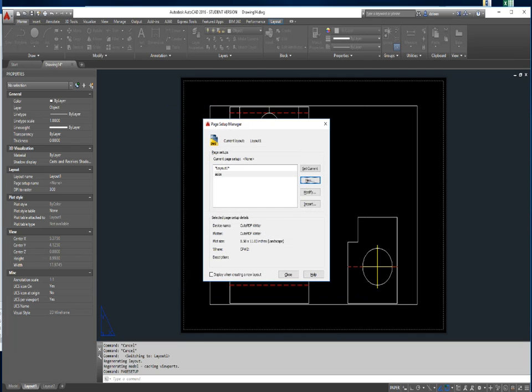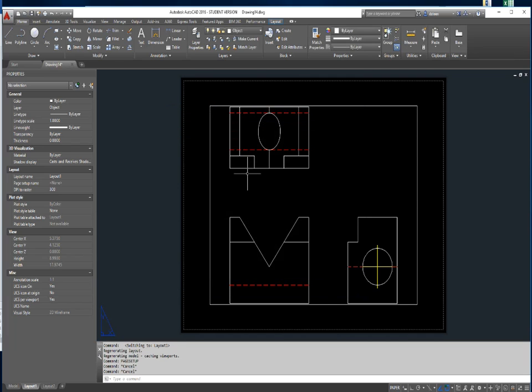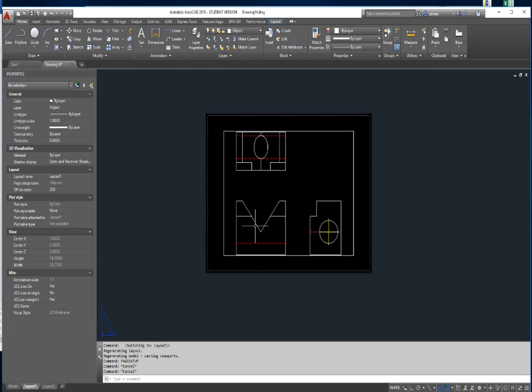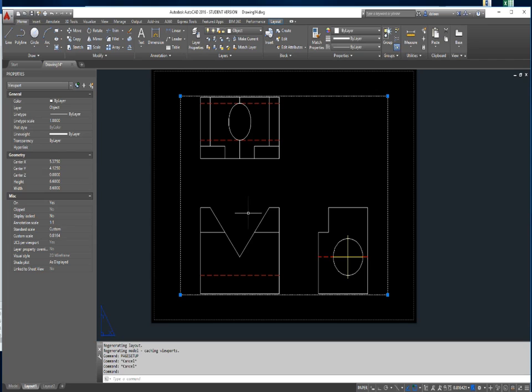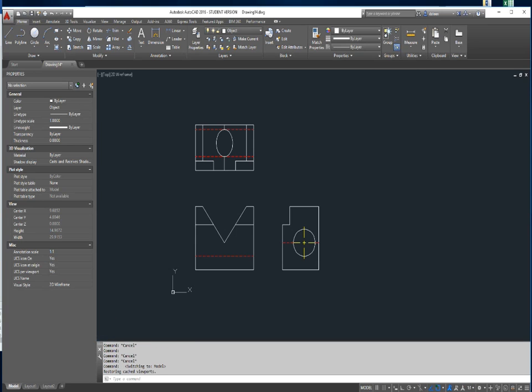But I'm just going to take this and identify a few things. So I'm in a layout view. Now that means I'm in Paperspace, sort of. So like here I can look at my UCS icon and I can go, okay, well I know I'm in Paperspace there. But then I have this white line drawn in Paperspace. And you can see there's the part I have drawn in model space.